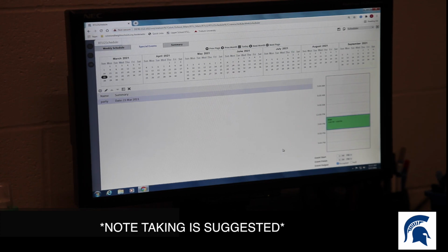Yeah, and if that's inside your regular schedule, like if you're gonna leave Saturday and Sunday from 5 to 6, then you wouldn't have to worry about the special event, it'll already be running. Right. But if you were to unoccupy completely over the weekend, that's when you'd want to come in and add this special event in there, to where it will kick on, even though its regular schedule's unoccupied, the special event would make it then turn on.